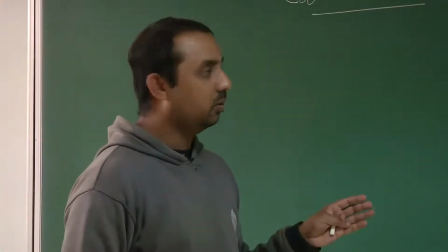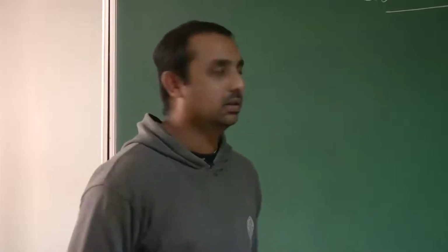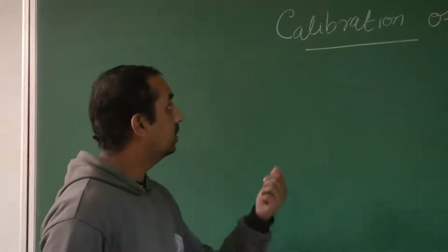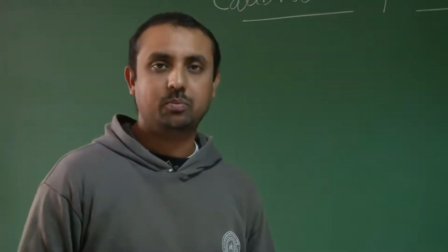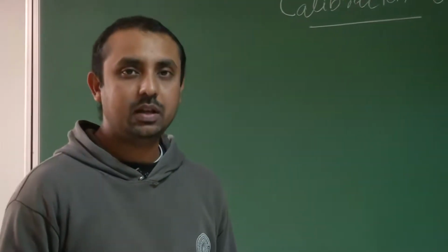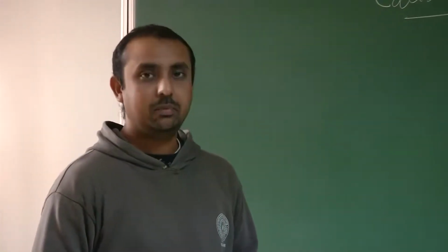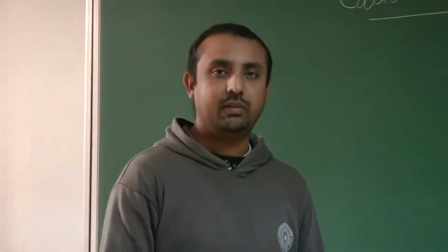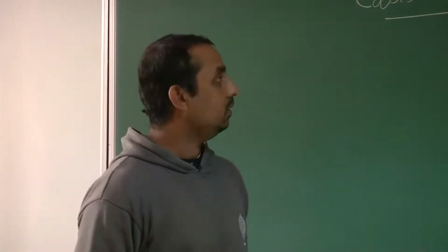Now before going deep into this topic, first let us understand what calibration means or why we do calibration. So as you know, calibration is configuring your result or output for a sample within a prescribed limit. For instance, if I want to sample my angle or deflection in the scale of voltage from 0 to 5, now I have to calibrate that control surface. And why we need this sort of calibration?